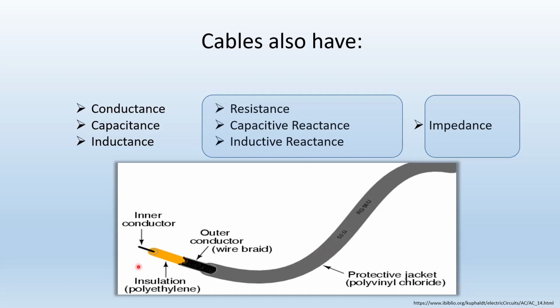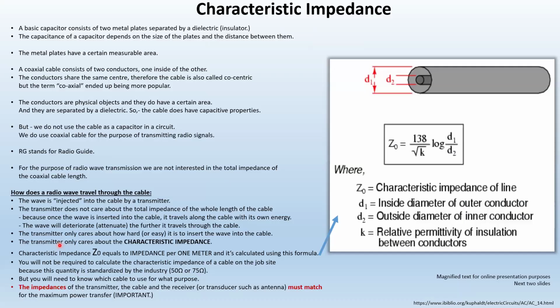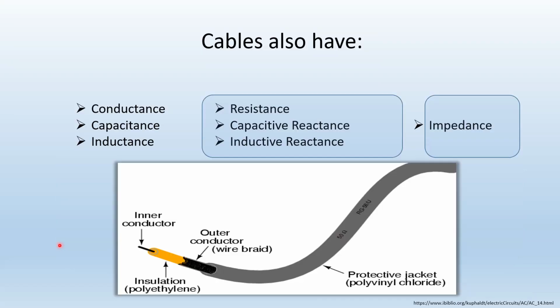So, there is a concept in electronics called maximum power transfer. In order to accomplish maximum power transfer, we need to match the impedance of the output of whatever amplifier and the input of whatever the amplifier services.